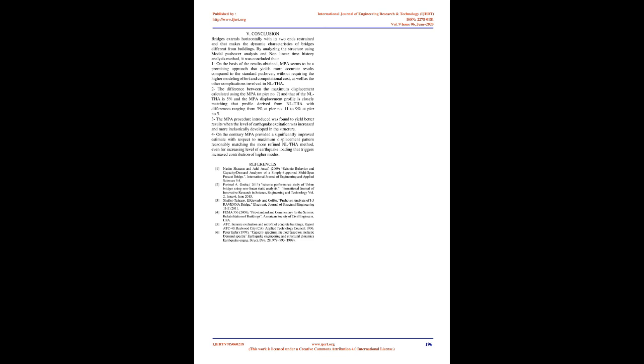MPA gives better results and underestimates the base shear by only 21%. It is observed that MPA provided better predictions, with differences ranging between 2% and 14%. Another significant advantage of the MPA method is that it is able to capture the plastic hinge development at P2 and P11. Hence, the overall degree of agreement between MPA and NLDHA is deemed quite satisfactory.